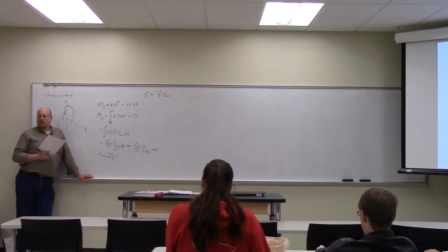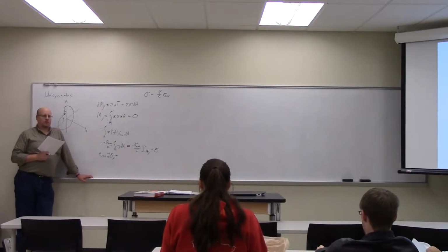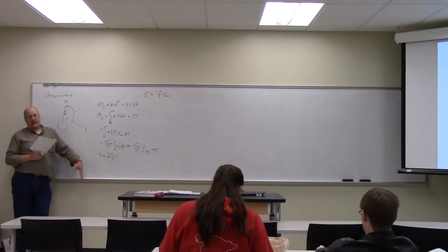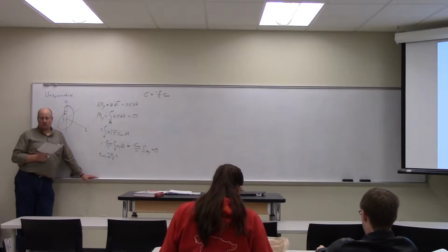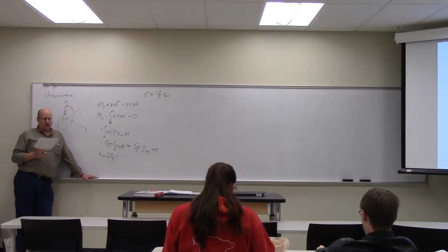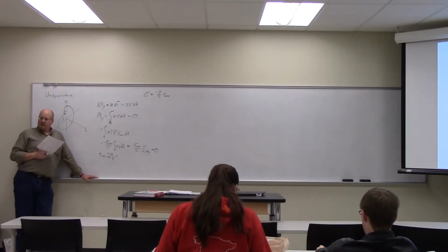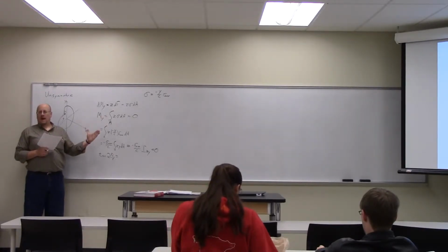So when we talked on Monday, we talked about the moments of inertia, right? And said that there's this moment of inertia, IZ, there's a moment of inertia, IY, and then there's a product of inertia, IZY. And we then did an axis rotation to Z prime, Y prime axes. You guys remember that? I didn't derive it, but I just gave you the final solutions, and I said that there is a particular angle at which you can rotate the coordinate system so as to have a minimum and maximum moment of inertia.